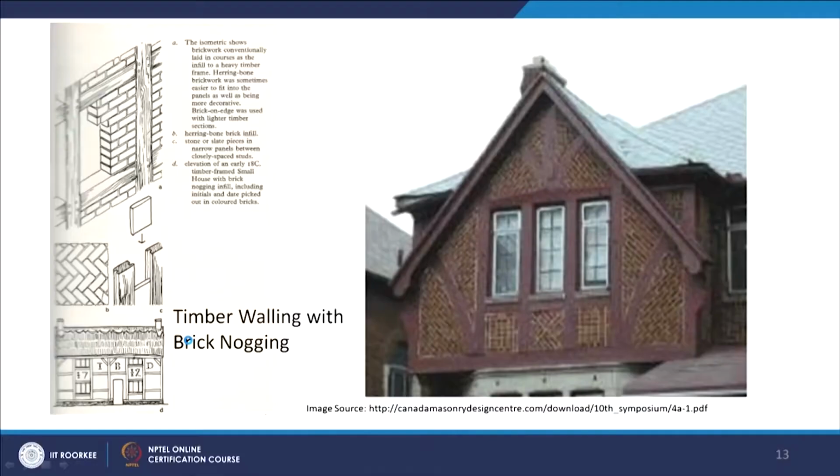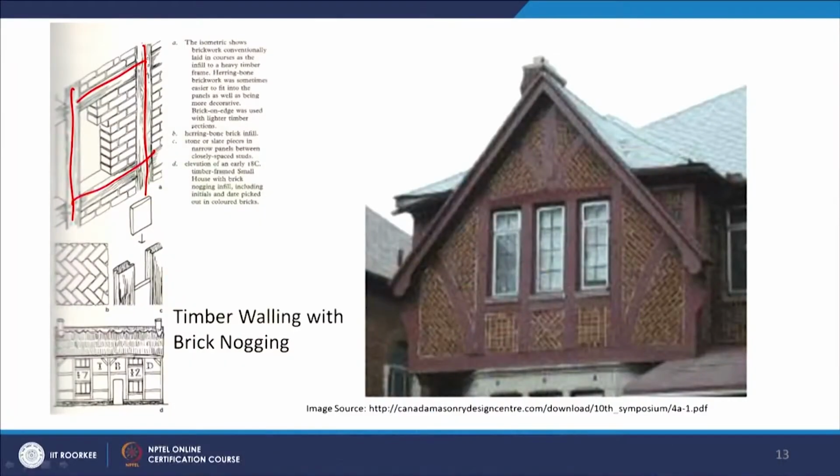This is one of the last I'm going to discuss here. And here, the same thing, you have the frame, and in between, sometimes even in the trusses as well, you can make different compartments, and you knock the brick in, and there are different ways one can infill these particular panels. Some of the techniques you can see: brick on edge was used with lighter timber sections, and as well as here, if you see the kind of compartments they can do.